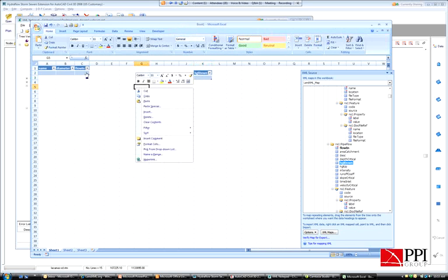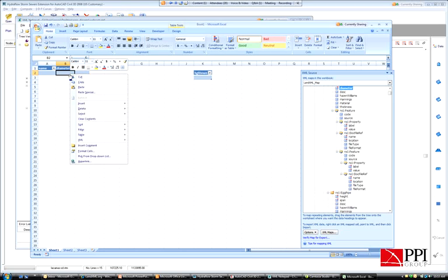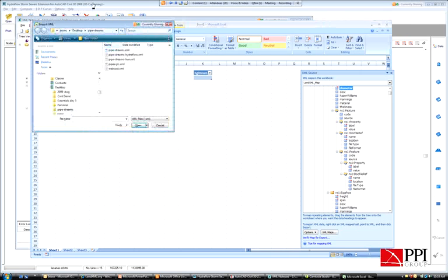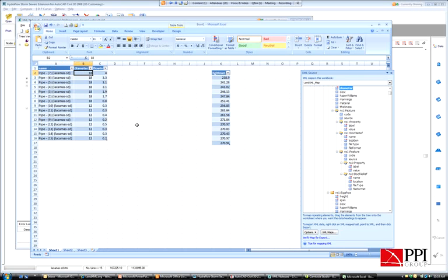And then once that's in there, you right click anywhere within one of the linked schema portions. And actually, so I go to my XML and I go to import. I'll go ahead and bring in this one, the pipe-dreams hydroflow, and import it. You can see it quickly populates those with all that XML data.